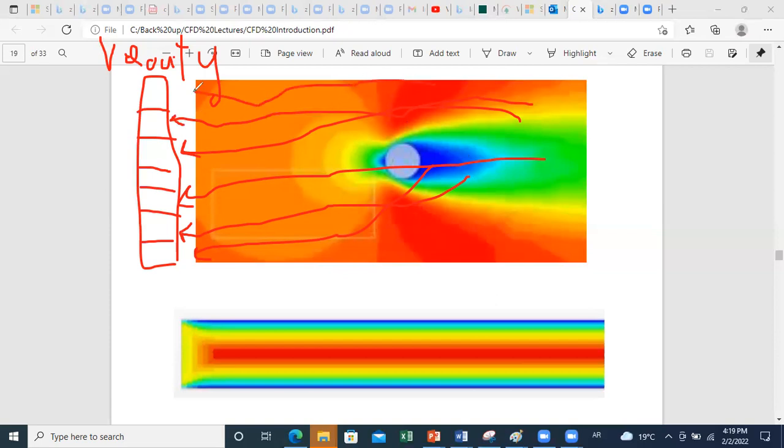Okay, now how did I know that this graph represents velocity? Who can tell me? Not pressure. No, stagnation point. Yeah, exactly. If you just observe the stagnation streamline, along the stagnation streamline, when you move, the velocity will decrease. However, the pressure will increase. So if this was a pressure graph, I should have another degradation of color. I should go from lowest to highest.